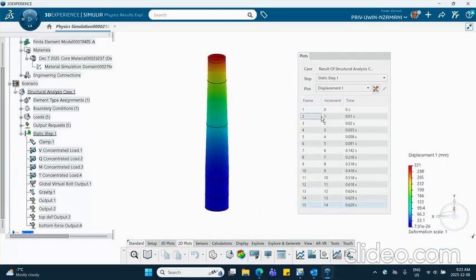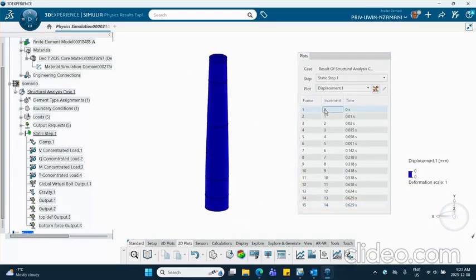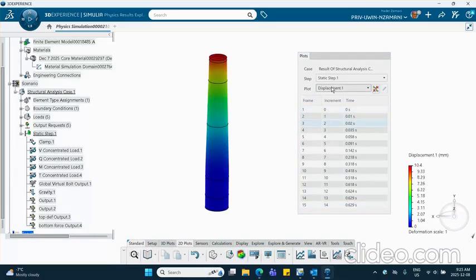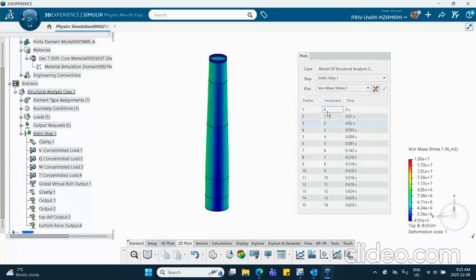All right, so this is the initial state, of course there's no deflection, and then these are probably elastic. Actually, let's find out. Let's plot the von Mises stress. Remember, the yield strength was about 345, I believe. So this is 19, elastic.